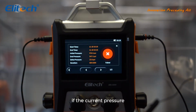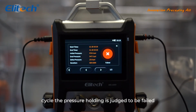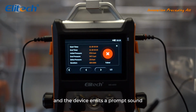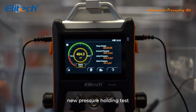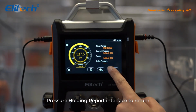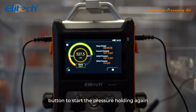a prompt sound. If the current pressure exceeds the leakage value within the pressure holding cycle, the pressure holding is judged to be failed. After the test fails, it jumps to the failure result display interface, and the device emits a prompt sound. You can also enter through the Report button to view the historical pressure holding reports. New pressure holding test. Click the Return button in the pressure holding report interface to return, and then click the Restart button to start the pressure holding again.